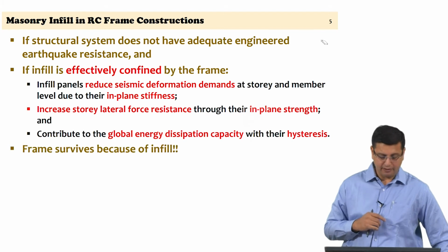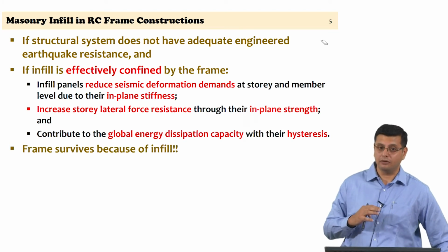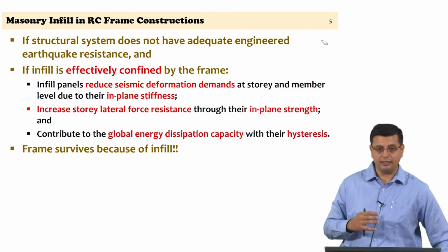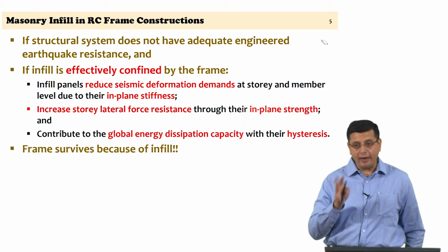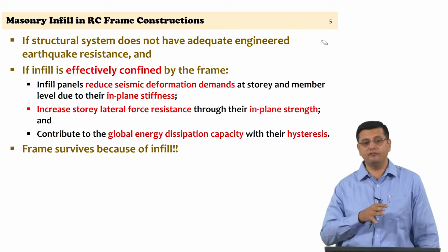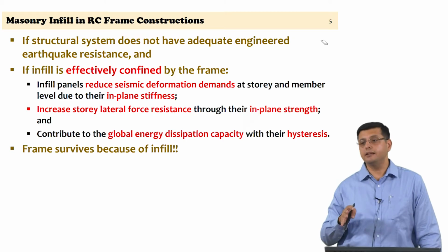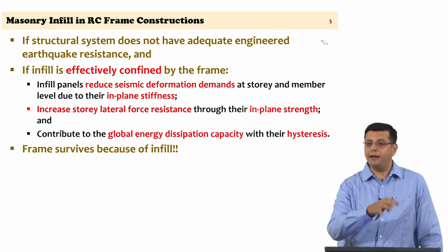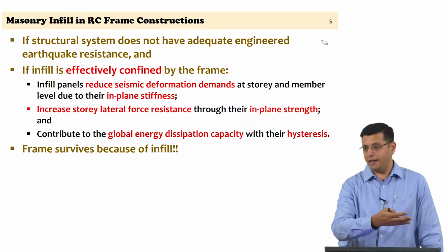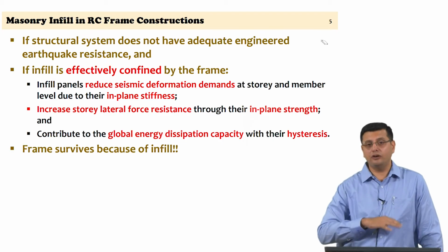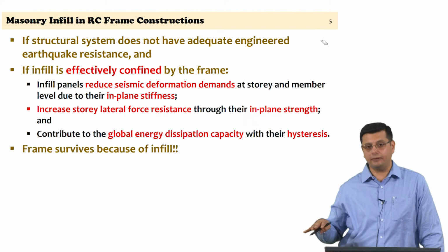So, that is the Indian context. It has been well documented in several of the recent earthquakes in the last few decades that the bare frame, if the frame did not have infill panels, it could have failed. But the presence of the infill actually limits the damage in the structure to non-structural damage, which is damage in the infills, and the frame has survived. And we are talking of frames which are not designed seismically.